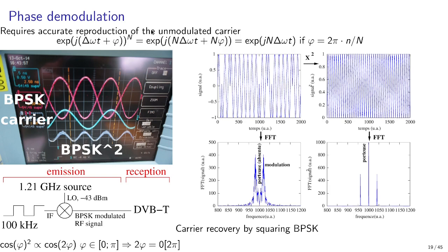So the output of taking the nth power of an NPSK modulated signal is a clean carrier, and this clean carrier will be at n times the frequency offset. If we know n times the frequency offset, then we can subtract the division by n of the frequency of a clean carrier and recover the initial phase information with no unwanted phase rotation.